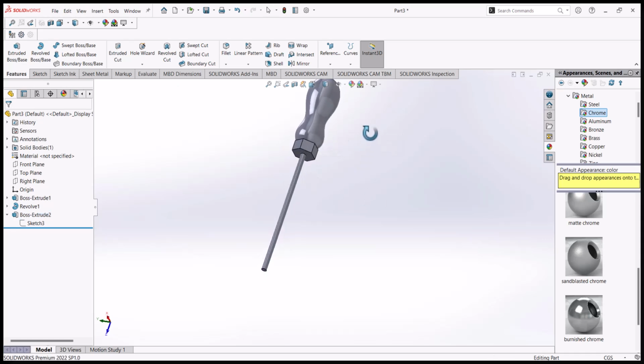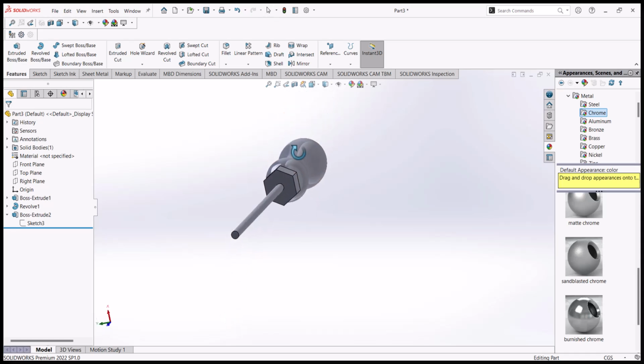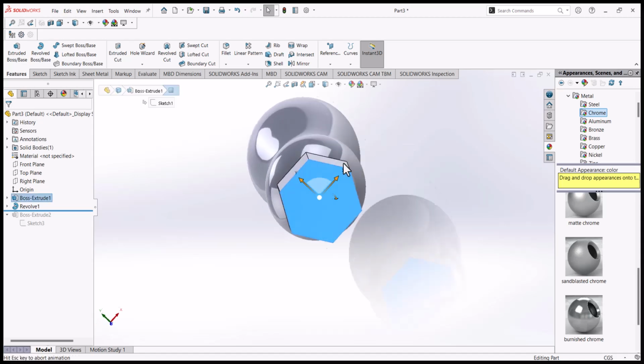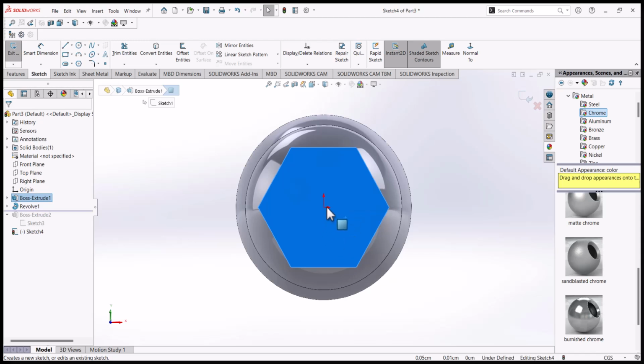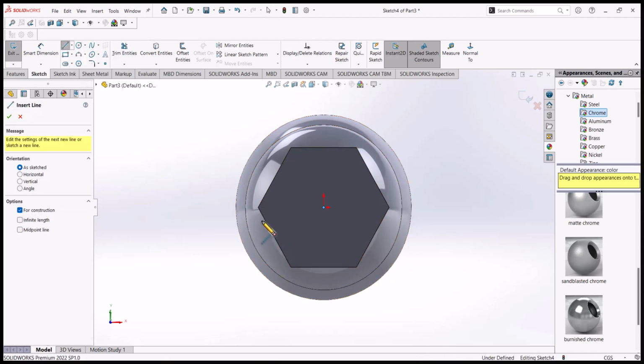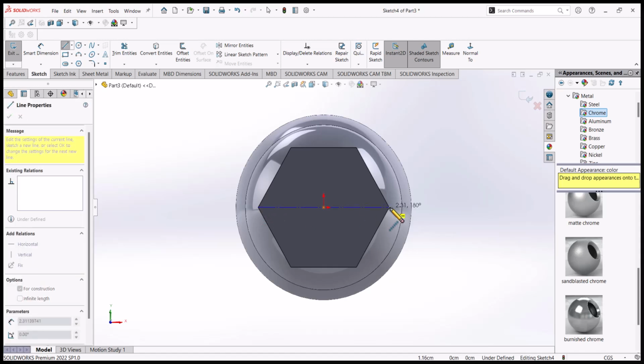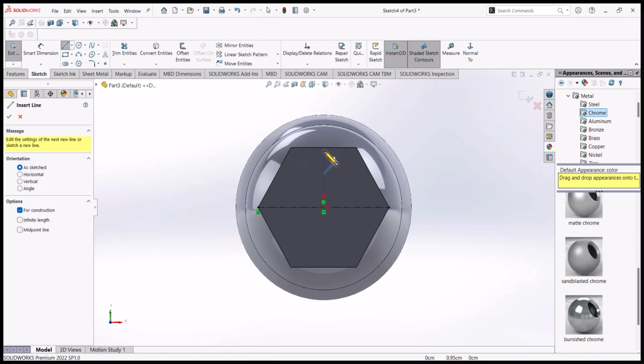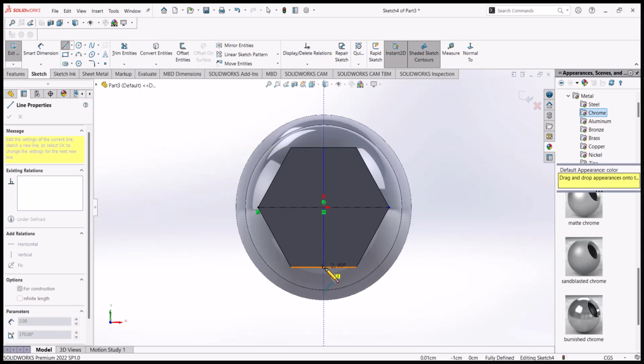Okay, let me show you. So let me go back. So I'll cancel. Let me go back. Good. So you see, I selected this edge. Then I selected sketch. Good. I started my drawing from the origin. So it means automatically this is the center. Do you get it? I can choose to do it like this. I can select center line from here. Select this part, then bring it to this part. Press escape, then select another center line. Then I select from the middle here to here. I still get a center.